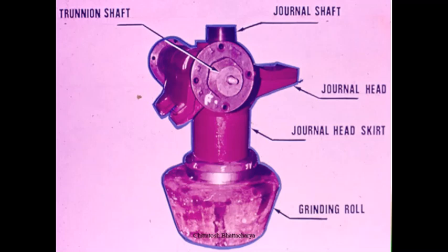that helps give the necessary loading for pulverizing. And this journal head can be tilted, and this tilting is provided to have a constant gap between the grinding roll zone and the bull ring segments. In general, we can move towards the center of the bowl or away from the bowl by adjustment of the lock nut from the top, outside the mill body.